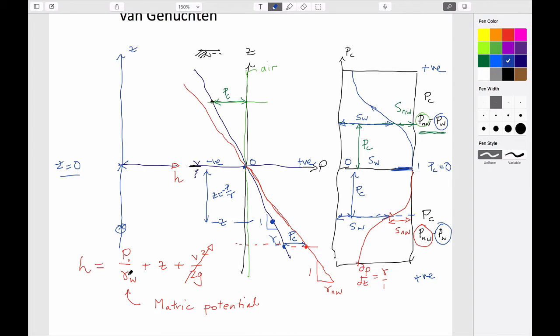So the pressure has to be equal to positive. So if the pressure at this point is positive, this decreases by the same amount that this increases by, and so you're exactly on this line. So the distribution of head at this point would actually be a thick line that is parallel to this. The head is constant, just as if you go in a swimming pool, the head is constant.